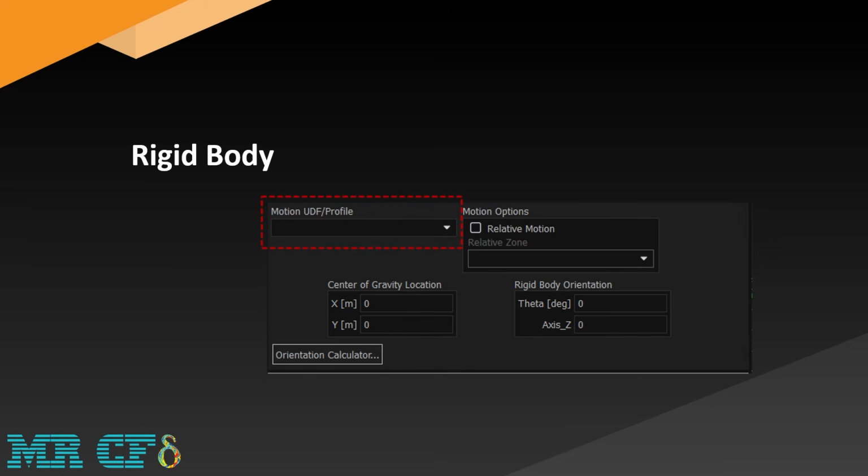When we use 6DOF, the translational or rotational movement of the object is defined by the degrees of freedom by the software, based on a series of data that we entered for the software in the 6DOF settings. While when we use the in-cylinder model, the software provides a self-generated function that is based on a series of data that we entered in the in-cylinder settings.